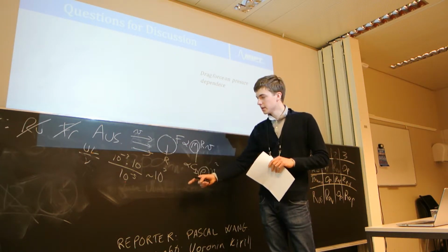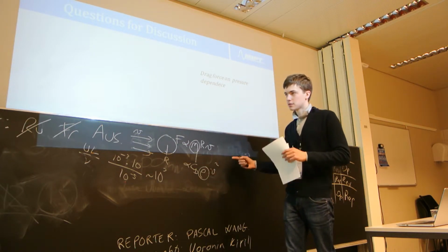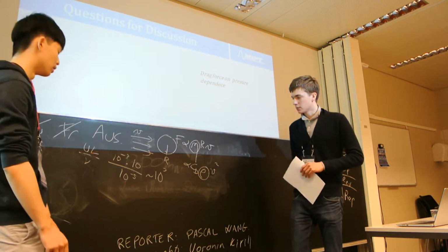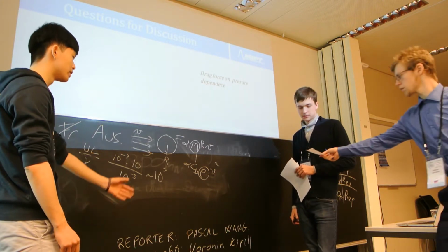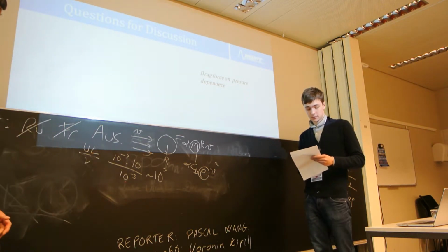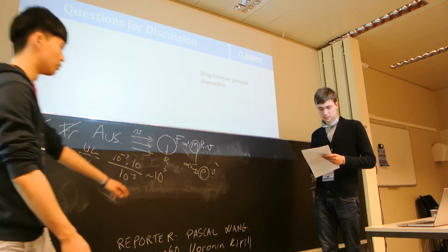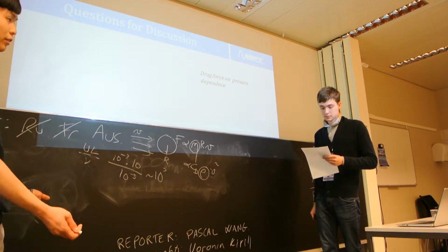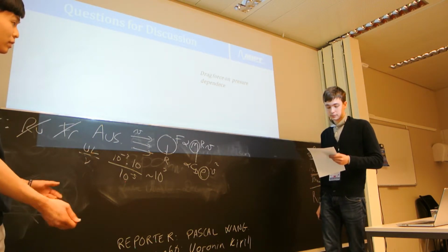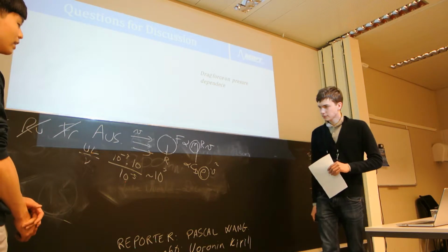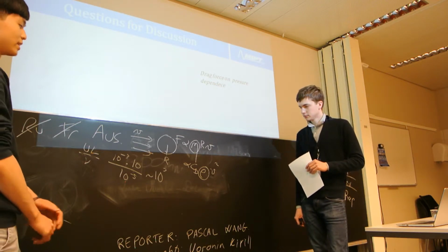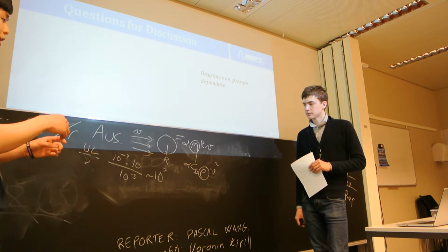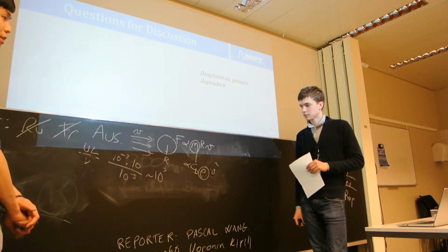From what Reynolds number does the turbulence mode start? It's around 10 to the 3, maybe more, 10 to the 4, in between these two. So when you have velocities of the order of 10 meters per second, 20 meters per second, then there is turbulence. But this is an effective force, which is an average of the microscopic turbulence around the fluid.